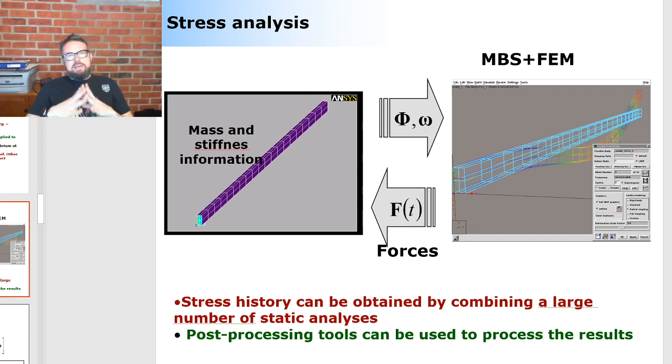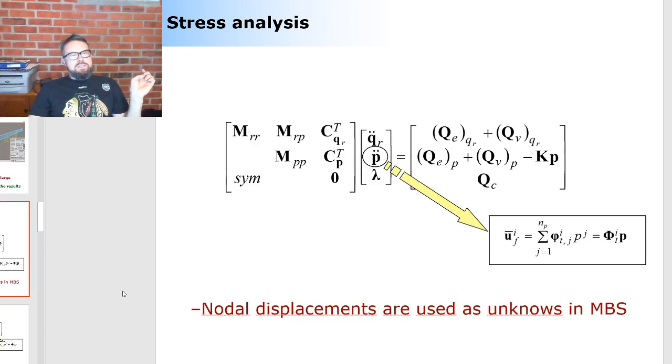So this sophisticated one, how does that go? Well, it goes such that you first have your finite element code, then you take the information about the deformation and put it in a multi-body code, and then, excuse me, this was still the previous case. So you still take this information to describe things in flexible bodies, and then the forces come back, and this is when you're computing all the stresses. Now the modal stress matrix. This comes directly from the theory of multibody system dynamics and the floating frame of reference formulation.